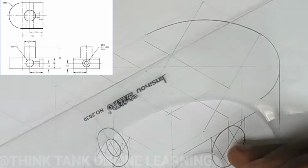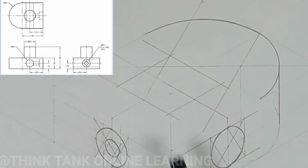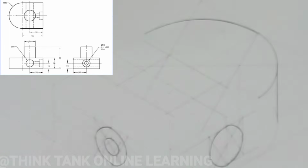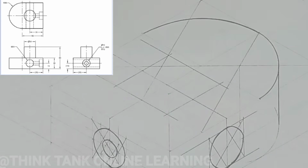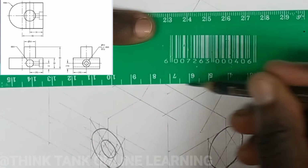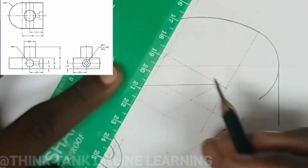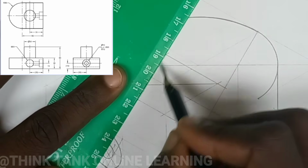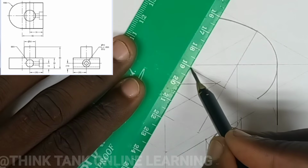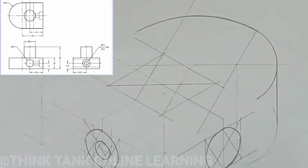Okay, so since we're going to draw the cylinder, we're not going to draw the full circle because the other part of the cylinder will not be shown. Okay, so you join the longest diagonal, which is this and this one. Now join this point and this point. Join this point and this point. Okay, and you mark your center 1 and 2.